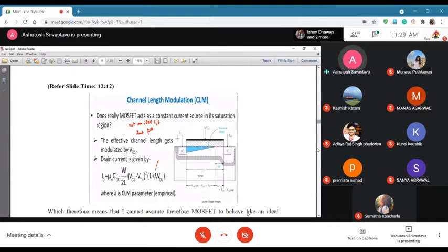Scaling down not only in terms of dimensions, but also in terms of field or voltages. So even voltages have been scaled down, and the effective field is also getting scaled down. That has been the driving principle behind the continuous scaling of your MOSFET based transistors.